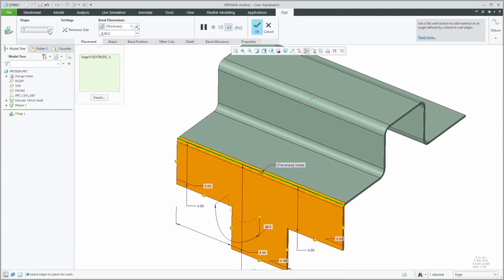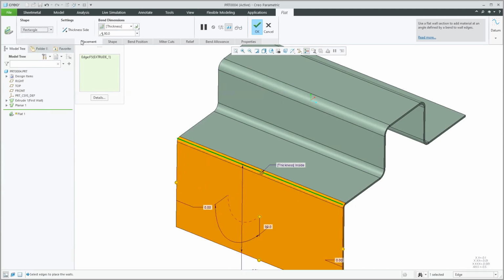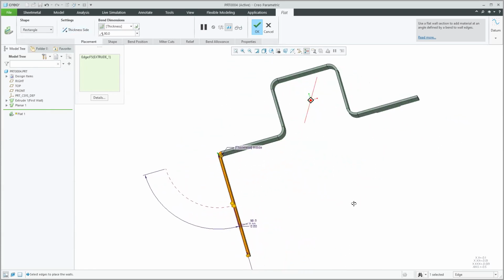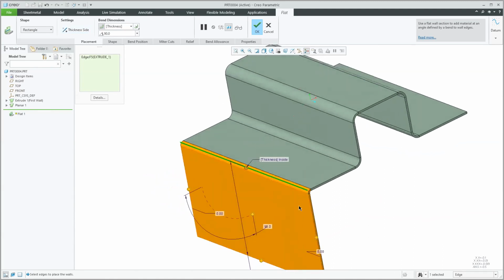Now, up above here, if I go back to just the rectangle wall, this is the thickness we discussed. The computer is keeping this sheet metal even. If I flip my thickness, it's adding the sheet metal thickness to the outside of the edge on here. And then we mentioned you could adjust this position. There is a bend position choice here. So it's currently even with the sheet metal.